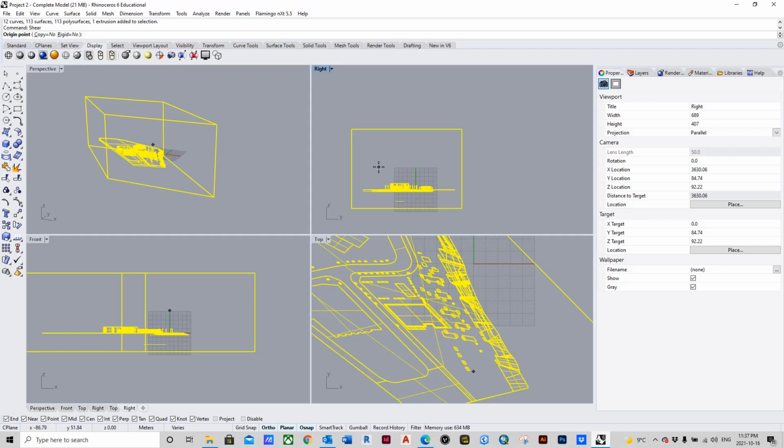And man, we sure are big fans of the lower left-hand part of this box, because that's exactly where we're going to click for the right-hand view. So we're going to move down to here. And like I said, you can tell, even though the perspective is getting a little warped, that's the right spot. So we're going to grab the lower left-hand corner of the box, left-click. It's going to ask for a reference point. And yep, this one looks good to me.